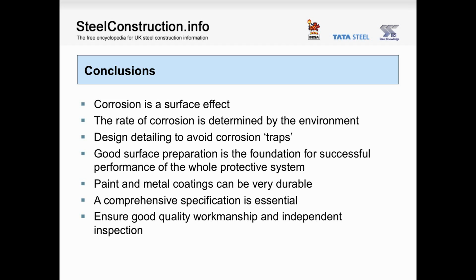Every part of the process should be contained in a comprehensive specification to enable those concerned to be clear as to what is required and when and who is responsible. Finally, the finished job will only be as good as the standard of workmanship from those employed. Appropriately trained and certificated operatives using reputable materials along with proper coating inspection will reduce the opportunity for premature failure and costly remedial works.